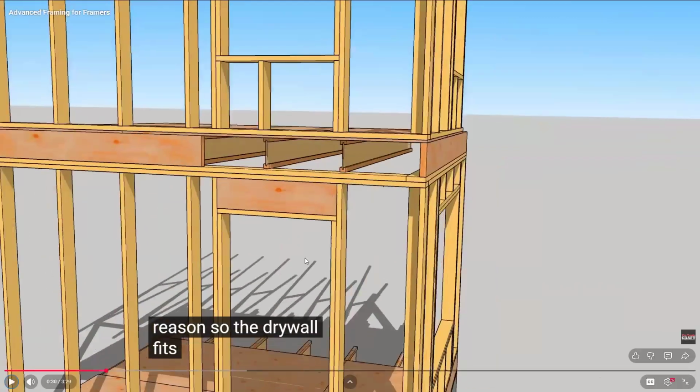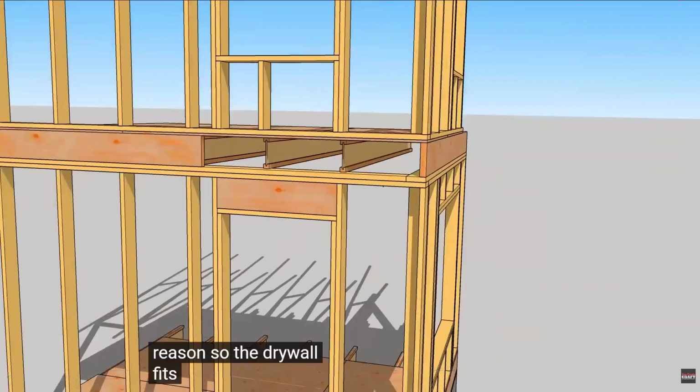So I'm just going to pause there. When he says so the drywall fits, remember what I just told you about the pre-cut studs? If you get rid of that double top plate, now your pre-cut studs won't work with the drywall. You have to trim all the drywall and your ceilings aren't at 8 feet, or you've got to cut all the studs individually to length to make the walls 8-foot 1 1/8.